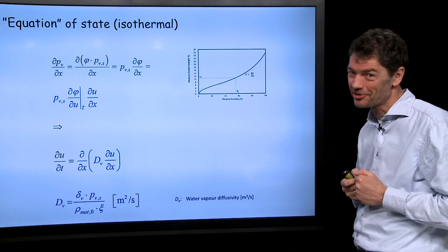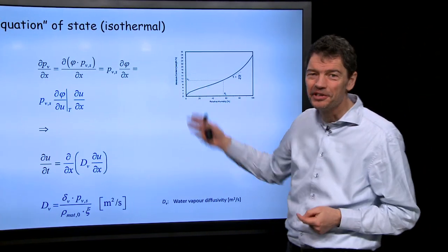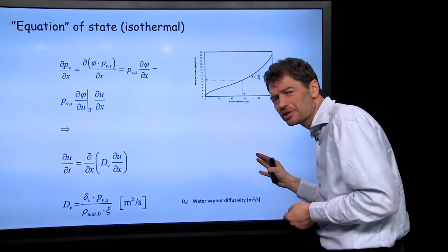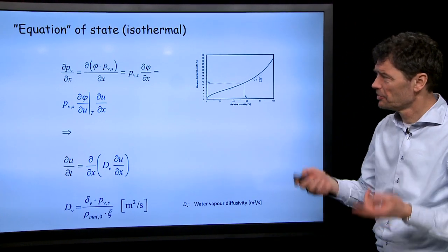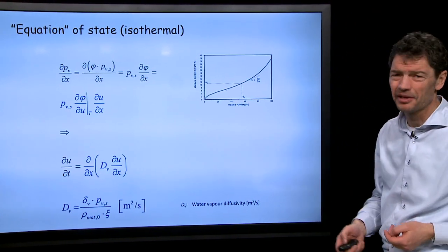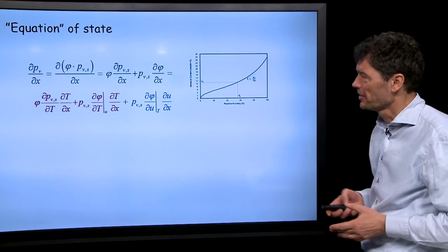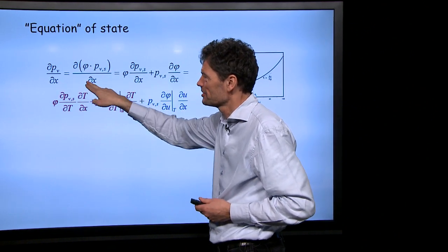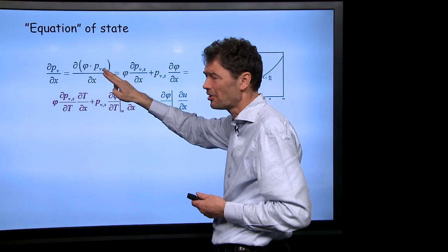And guys, I promised you to show it with some couplings. So what happens if we have varying temperatures? So there is not only a moisture gradient across the material, but at the same time also a temperature gradient. And that I will now reveal in this system of defining things on the last slide here. So we write everything again. We start the same way. The gradient of vapor pressure we express as phi times the saturation pressure that we take the gradient of.